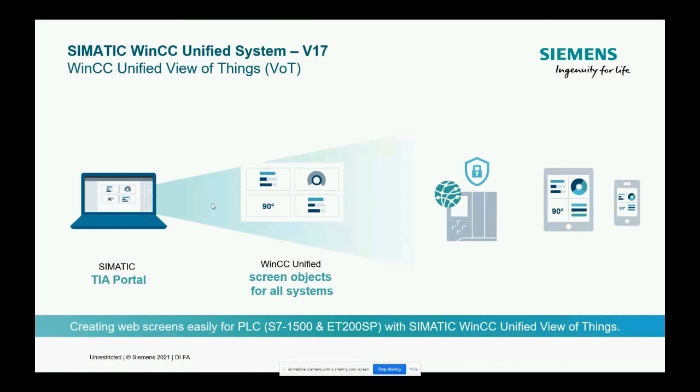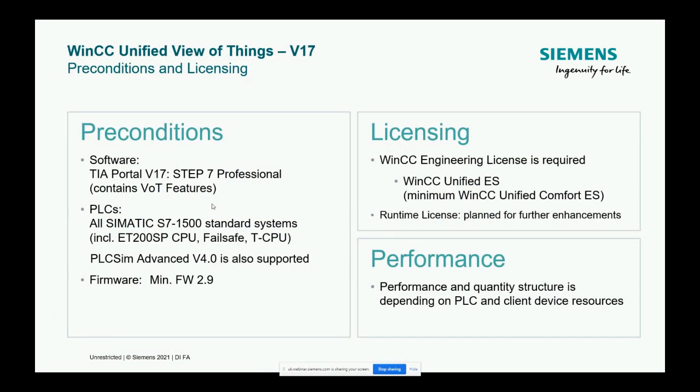So what is it? First of all, it's based on TIA Portal. We use the WinCC Unified screen objects, and what we're actually doing is configuring the web server on the S7-1500. So we're not creating a new runtime, we're just configuring the web server that was, to be honest, always available within the S7-1500, but previously you had to really get into the HTML5 code to program anything on top of this. So we can create web screens based on the S7-1500 and the ET 200SP controller. The S7-1200, for instance, is not currently supported with WinCC Unified View of Things. There are some limitations and preconditions in terms of what we can do.